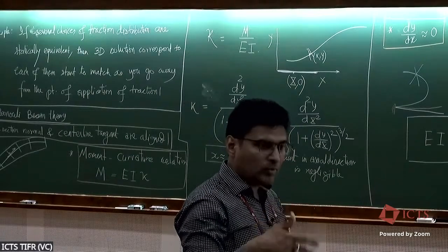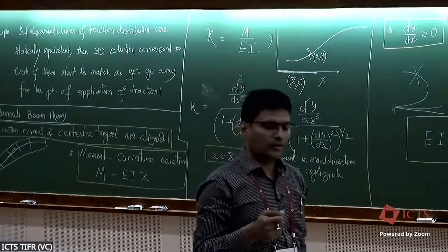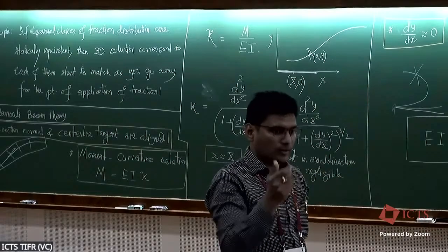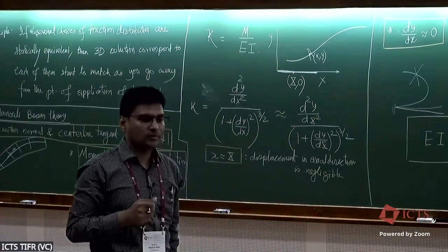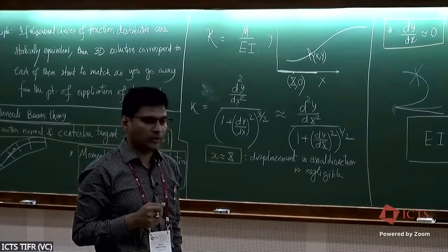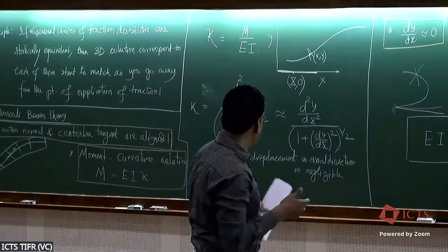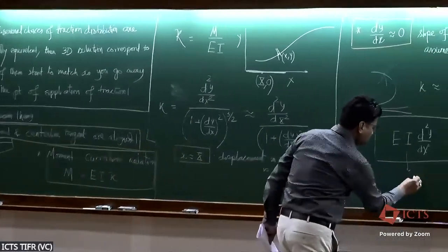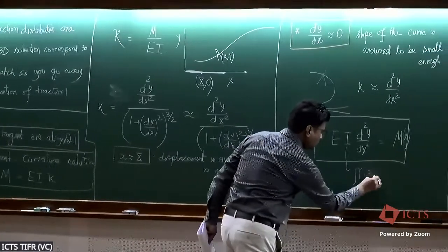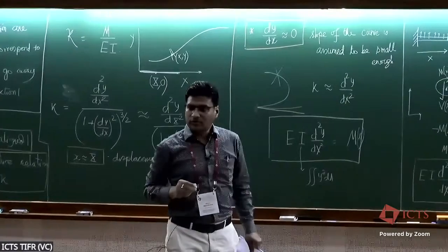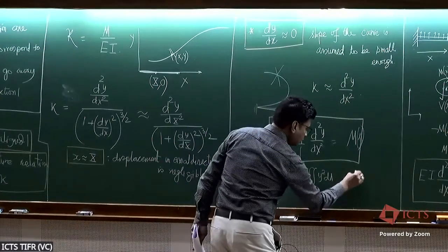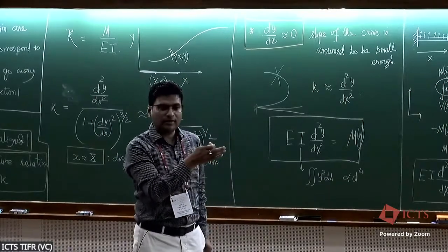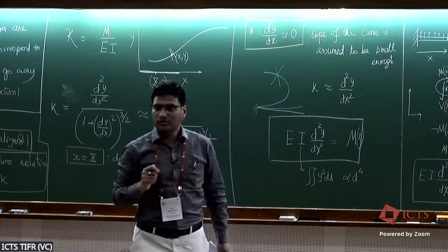I is the second moment of area, which is again a geometric property. Square, the D4? A is the area, so it is D square. I goes as D4. That's a very good question, and everyone should know that I, where is I? Here. That's actually the second moment of area, no? It's y squared dA, for example. So it scales as D to the power 4, whereas the cross-sectional area scales as D square.